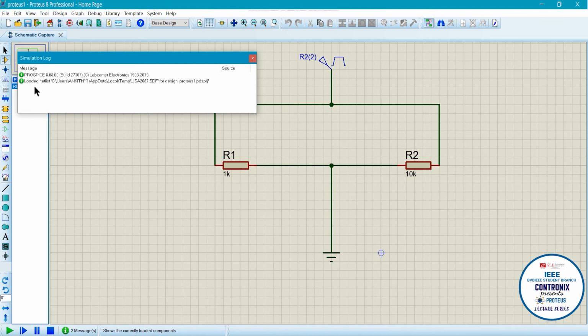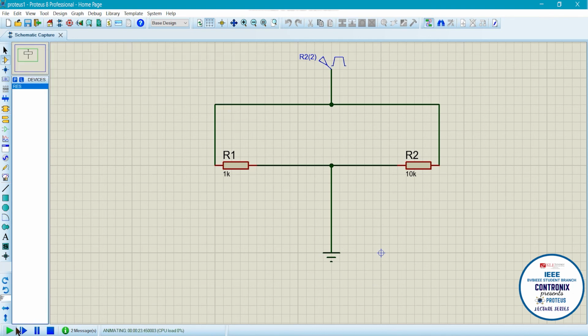If you see a yellow, that means there's a warning, and if you see red, that means there's an error in your connections and you should not do the connection like that. Please check your circuit again and try to fix the problem. Now, I can pause the simulation at any time and rerun it again. If you're using a voltmeter or ammeter, you can pause and look at the value and note it down at each and every point of time. So this would be really useful and it's not possible in real life. Now if I click on the square, it will terminate this process.